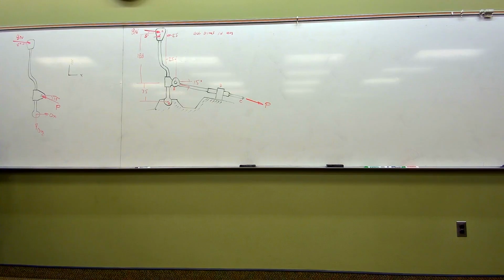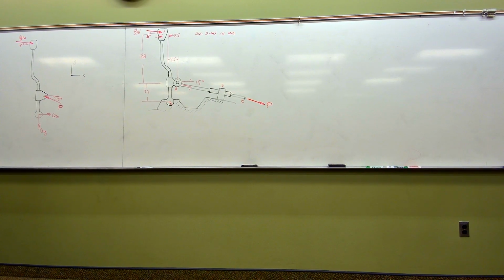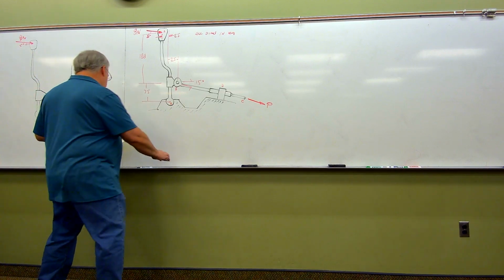And now, folks, if you take a look at that, you'll realize that's a complete free body diagram. So now, what went from looking pretty messy over there has gone to one free body diagram with, in this case, 1, 2, 3 unknowns, but following the theme of the past two problems, we don't even need to do anything more than one moment equation about point O right here, because I don't care what OY is, I don't care what OX is, I was asked to figure out what P is, and one equation is going to get me there.